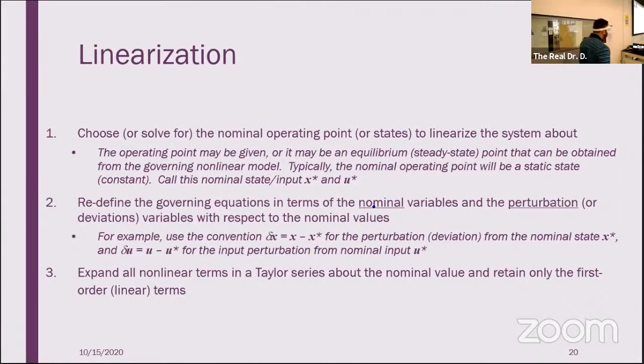And then we're going to expand this new equation using the Taylor series and evaluating at our nominal value. We're only going to keep the first order linear terms. Why? Turns out that as we move through the Taylor series, the higher order terms, yes, do they make our answer more accurate? Sure. But they don't add enough to warrant keeping them.